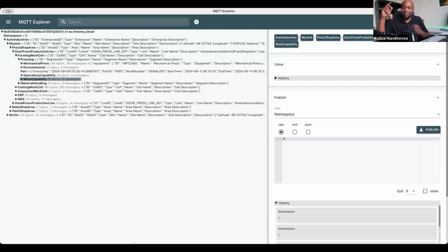So you want the timestamp for each metric, and then you want a timestamp for when that information was pushed out as an object. So you've got two levels of timestamp: collection time and publishing time. Maybe look at Sparkplug for inspiration on how to structure your timestamps, because that's the exact principle Sparkplug follows.